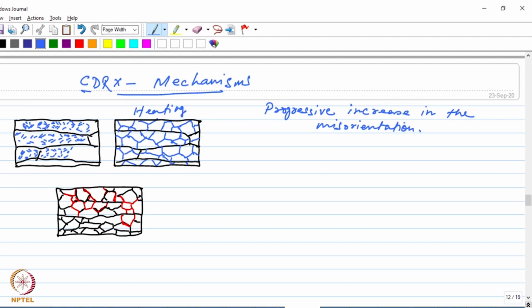So when you have heat being applied simultaneously, contrary to the cold worked structure that you might have when the material is deformed at cold conditions or at temperatures below the recrystallization temperature, you will have this kind of well developed dislocation substructures with low angle sub-boundaries formed by the dislocation rearrangement. And that's the dynamic recovery process, as I said.